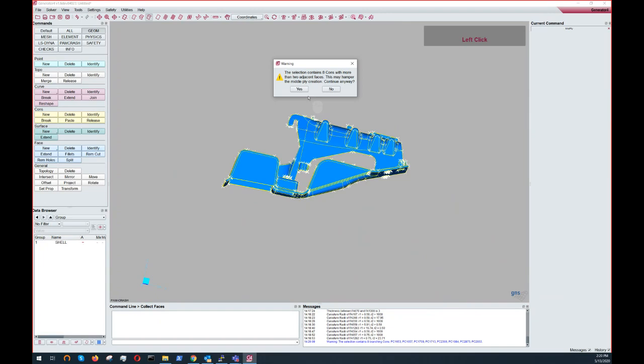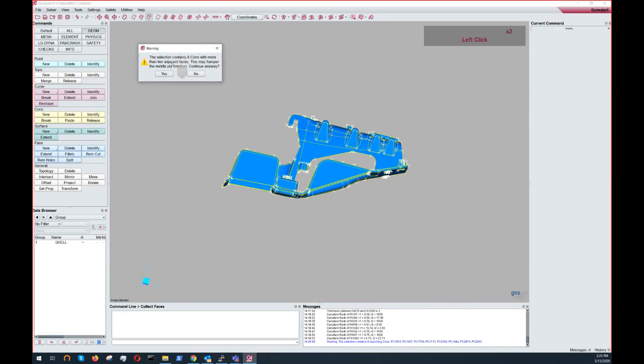It tries and creates a multiply, but depending on how clean this geometry is, maybe there are some, so it reflects on the results. So it says, okay, there were some triple cones there. This may hamper the results, but do you want to continue anyway? Yes, in this case, there are just 8 little cones. I don't know where, just little. So basically the geometry is correct. So I can say, okay, go anyway, try.